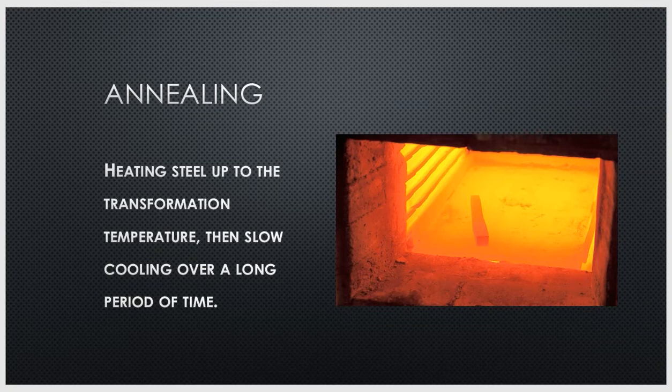Now, depending on what exactly you're trying to achieve, you could control the cooling rate to a matter of hours, or you control the cooling rate to, say, something like overnight. It just depends on what you're trying to do. So remember, annealing, you're heating it up, keeping it there, and then you're forcing it to cool down slowly.